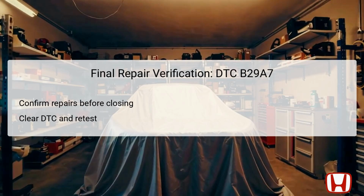Once you believe the system is operational, the next step is to clear the DTC using the vehicle's onboard diagnostic system. After clearing the code, retest the climate control system thoroughly, monitoring for any recurrence of the issue. This final test is crucial as it validates the effectiveness of your repairs, providing confidence that the problem has been resolved.